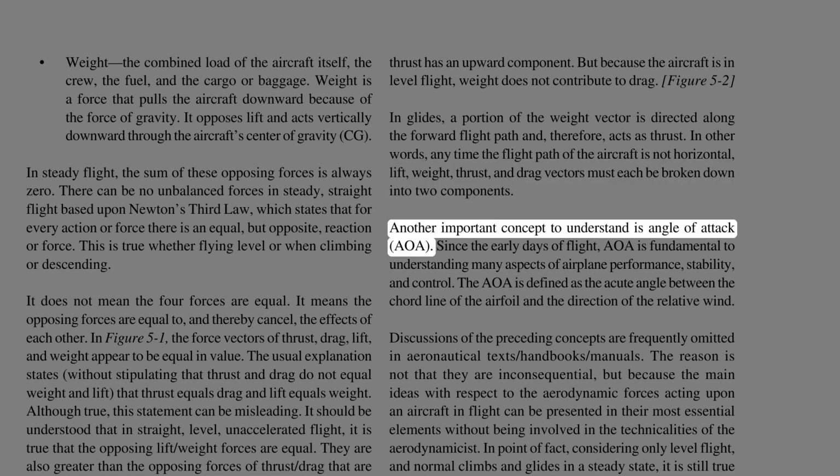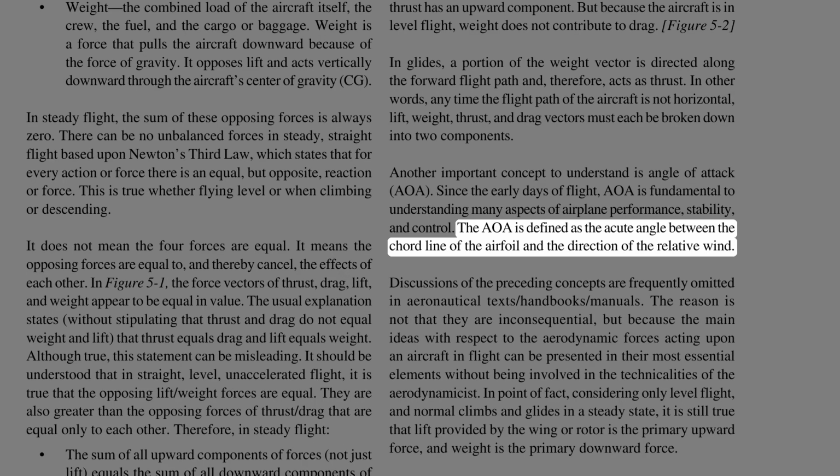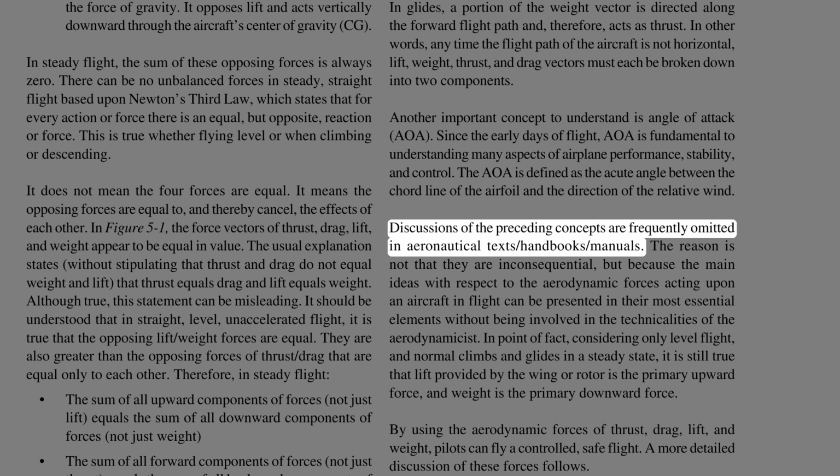Another important concept to understand is angle of attack, AOA. Since the early days of flight, AOA is fundamental to understanding many aspects of airplane performance, stability, and control. The AOA is defined as the acute angle between the chord line of the airfoil and the direction of the relative wind. Discussions of the preceding concepts are frequently omitted in aeronautical texts, handbooks, manuals.